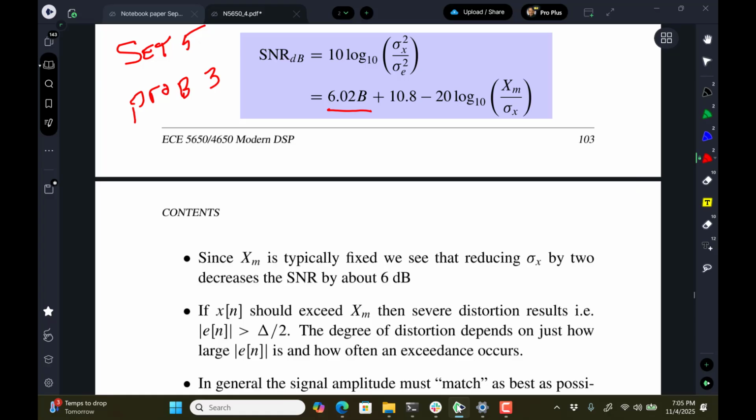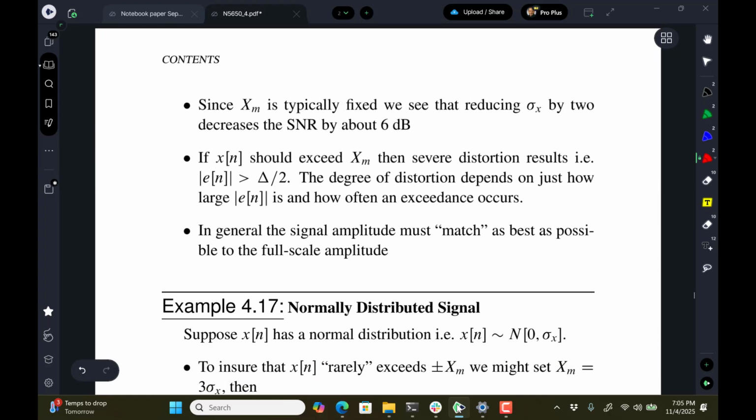One of the things about the quantizer, and what I was talking about in the Python model, is how do you deal with overflow? Do you have rounding if you have 2's complement? Or do you have saturation, or do you let it overflow and become negative, which is a very gross distorting type error? So you really want to match as best as possible.